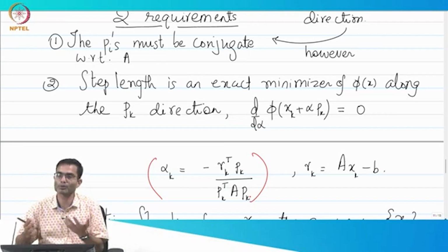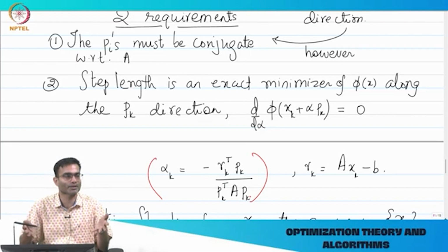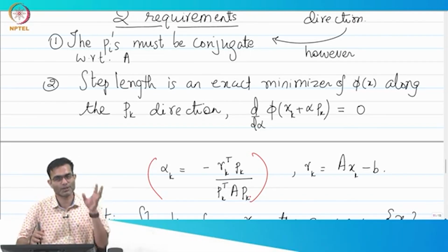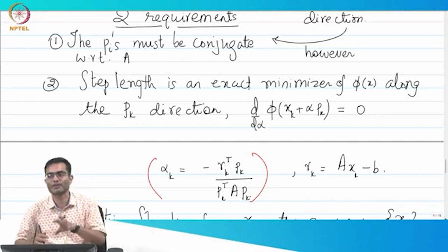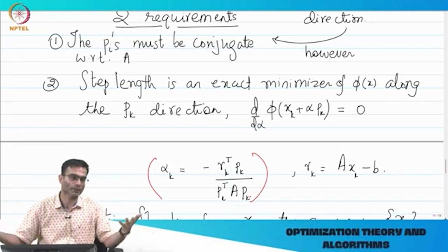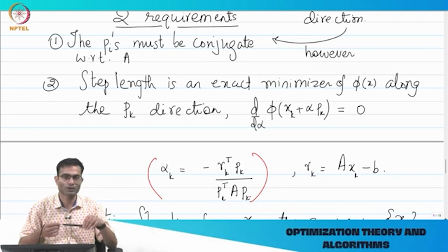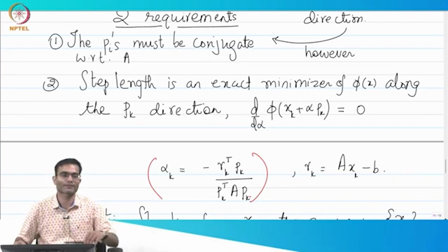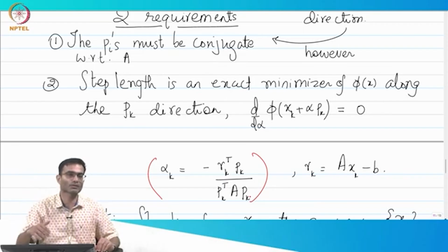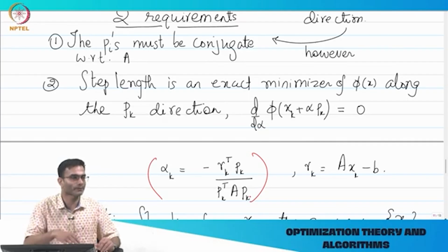So, if I am able to do matrix vector products, this expression is fully made of matrix vector products and vector products. So that's why iterative method is specifically designed for places where you run out of memory and you cannot do the whole thing directly. It will take more time than a direct method, but you have no option. Okay. So those of you using commercial software for solving systems, if you see the log, it will say using this indirect solver or that indirect solver. This is one of the methods in between.